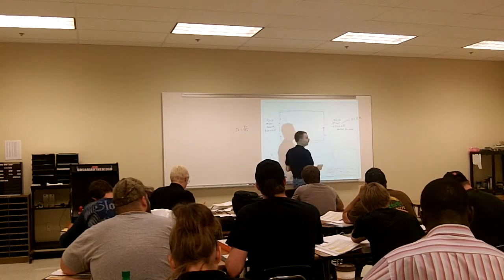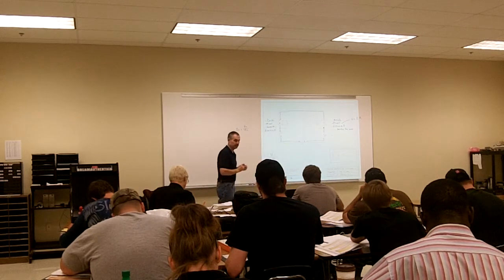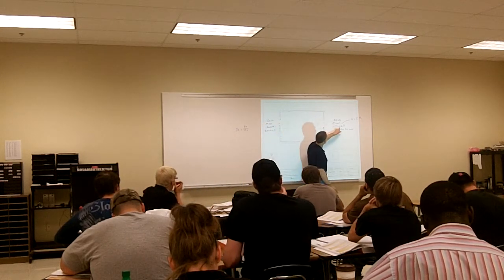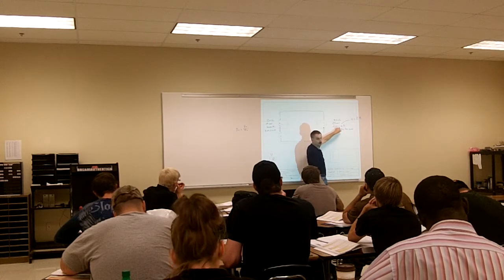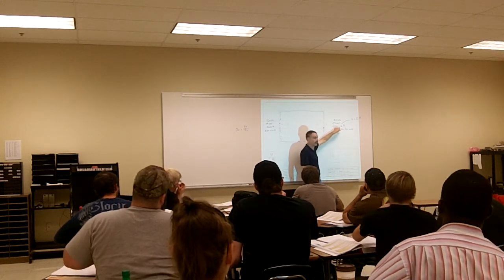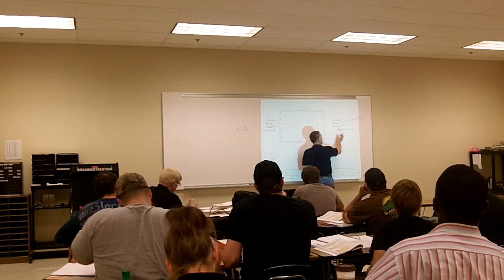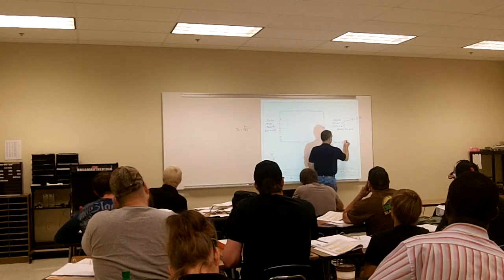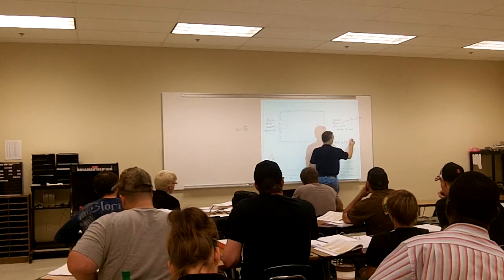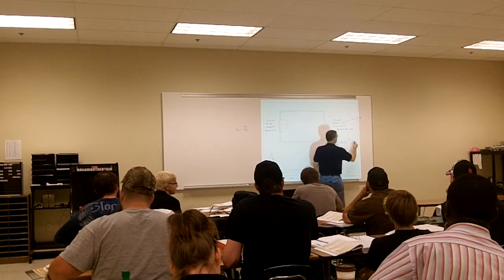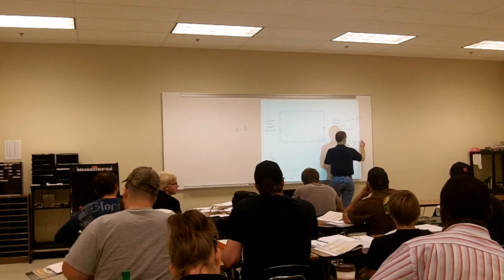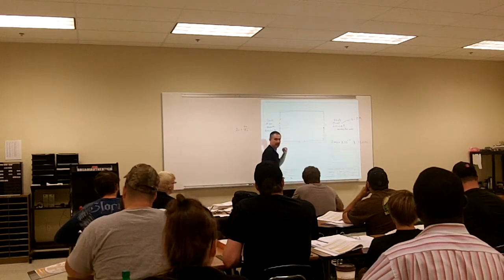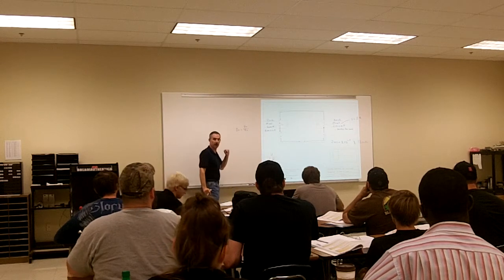Should be 24 volts. The problem is that you're not using your exponent. You've got to make sure that when you put it into the calculator, you're hitting 200 times 10 to the negative what? Negative 3. Times my resistance of 120 ohms. Does everyone know how to use their exponent key? Put it in the power of 10.